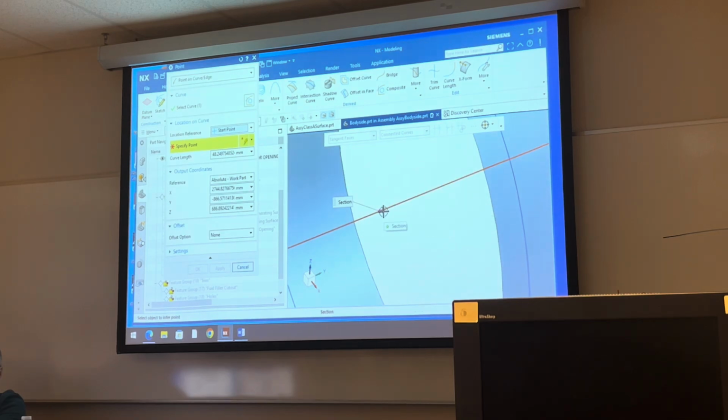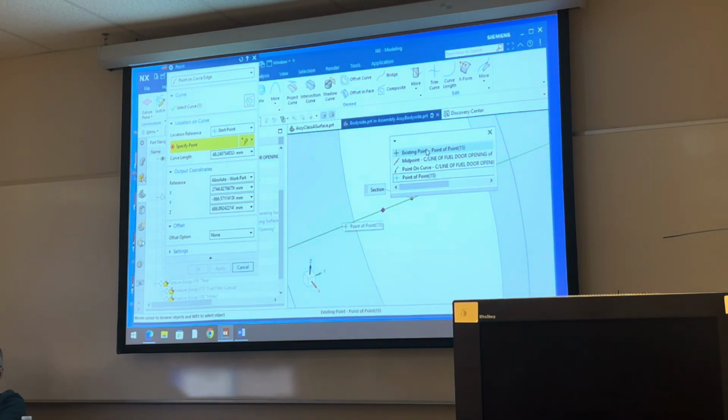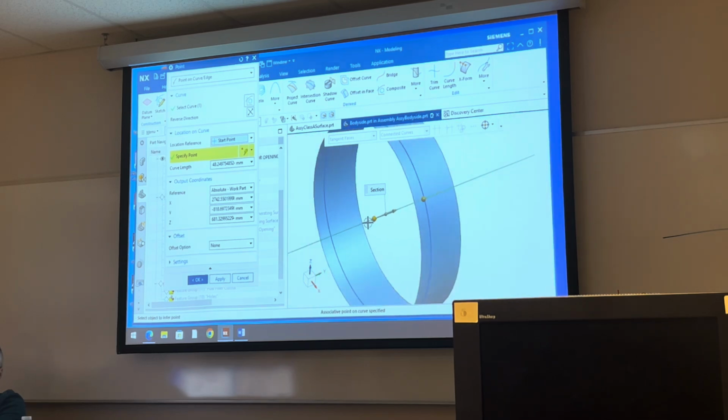Okay, I'll wait for the 3 dots. It almost looks like it's not letting me pick it. Go back there. There it is. Sometimes it's weird. If it doesn't let you pick it, wait for the 3 dots. Pick it from the tree. You can't go wrong that way.